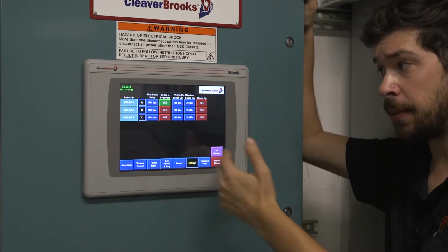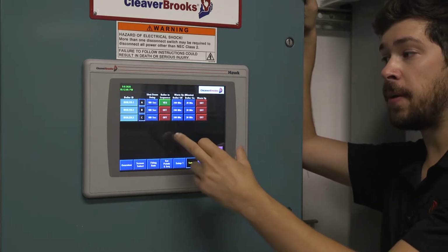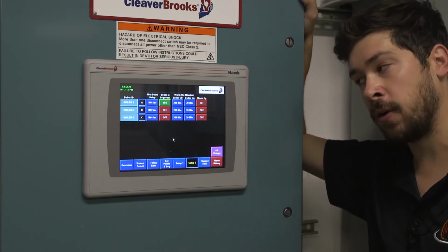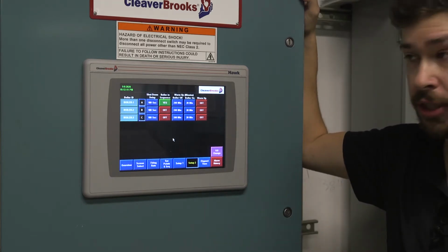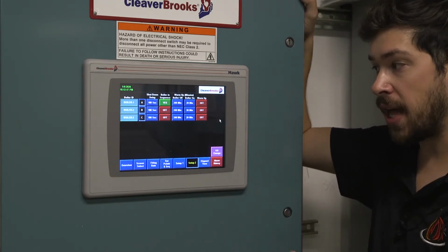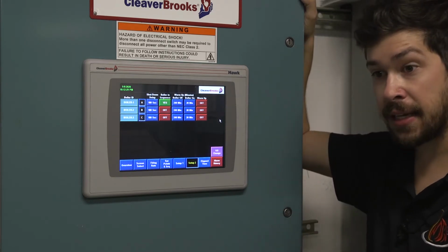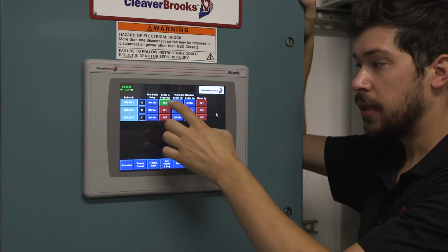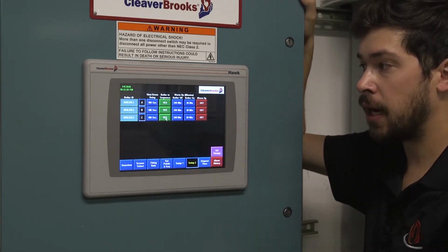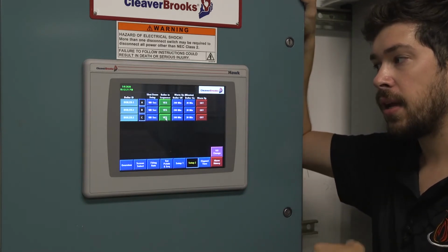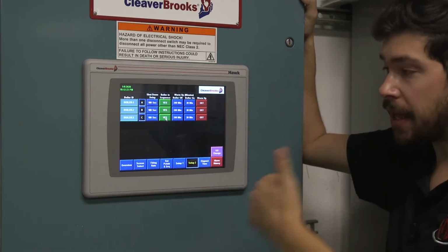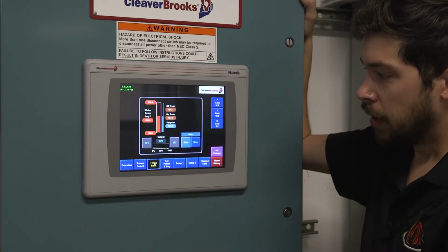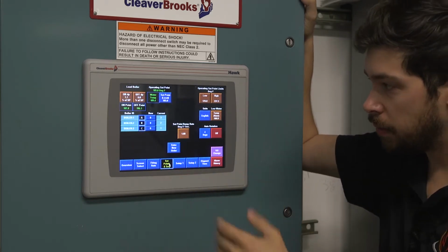A little bit easier to come up here in one single spot, but the benefit here is with that burner switch on the boilers, you'll keep that isolation valve cracked open and you'll continue to have flow through it, which will keep the shell warm. That whole thought process of keep the isolation valve cracked, keep water flowing, is why we opted not to do this. So simply coming in, taking these off sequence is a little bit better way of doing things than walking up to the burner itself. It's a little bit easier.